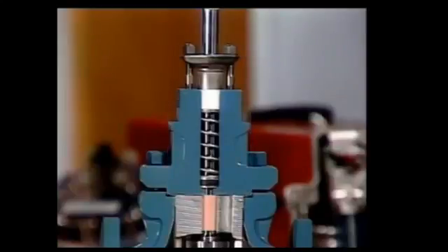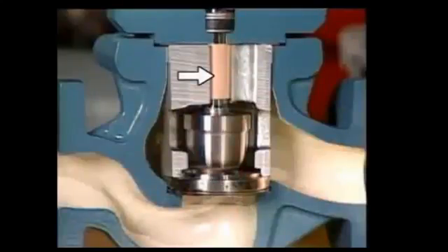Control valves also have parts that may not be on manually operated valves. For example, control valves, like this one, generally include guides that align the valve stem and disc with the valve seat. These guides help ensure precise control when the valve is opened and closed. The upper stem guide on this valve is housed above the packing inside this part of the packing assembly. This is the lower guide, which is held in place by this part of the valve called a cage. Part of this cage, along with other valve parts, have been cut away to better show the valve's construction.